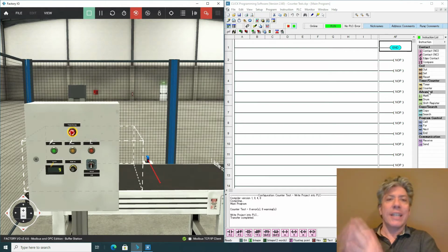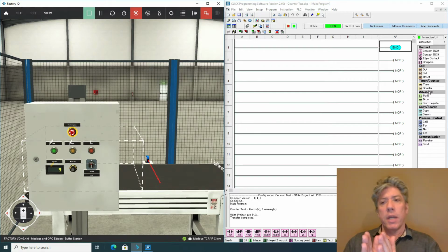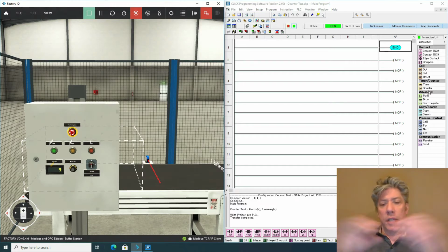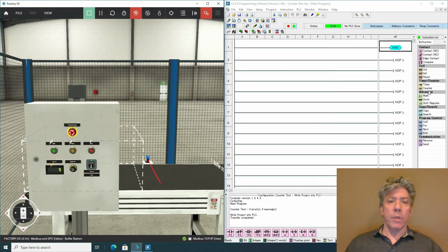Now, technically, all of the items in the PLC are zeros and ones, but the thing about a timer and a counter is it deals with more than 1, 0, and 1; that really represents a number. So we don't think about it as bits so much anymore, although that's what it really is in memory. We think of this collection of bits as a number that represents in the timer how much time has elapsed, or in the counter how many items have gone by. Now, the interesting thing about timers and counters is they're typically used as outputs, but they also have inputs.